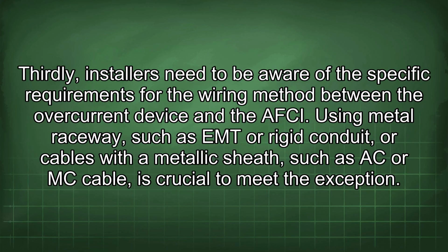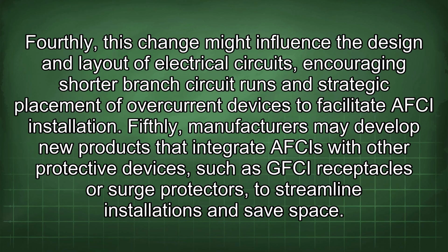Thirdly, installers need to be aware of the specific requirements for the wiring method between the overcurrent device and the AFCI. Using metal raceway, such as EMT or rigid conduit, or cables with a metallic sheath such as AC or MC cable, is crucial to meet the exception. Fourthly, this change might influence the design and layout of electrical circuits, encouraging shorter branch circuit runs and strategic placement of overcurrent devices to facilitate AFCI installation.